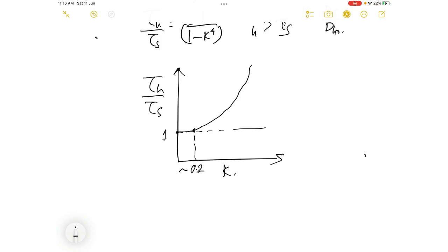So basically it did not do much in terms of an increase in the torsional shear stress, but rather it helped us to reduce the weight. And why is it so important? Because they have mentioned this condition that we are going to implement this shaft for the spacecraft application. So weight reduction is one of the primary concerns, and if you are able to even bring about just 3 to 4% reduction in the weight of any component, then you are doing remarkably well.